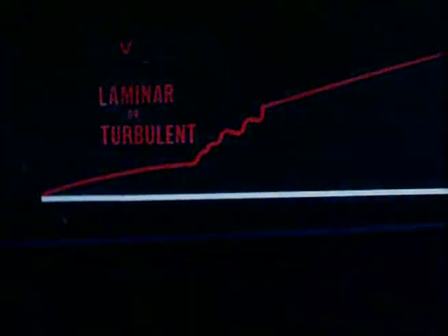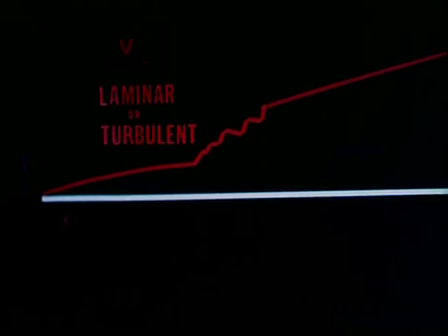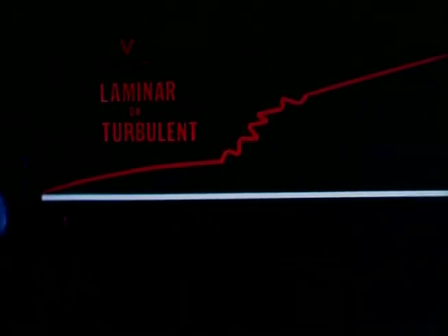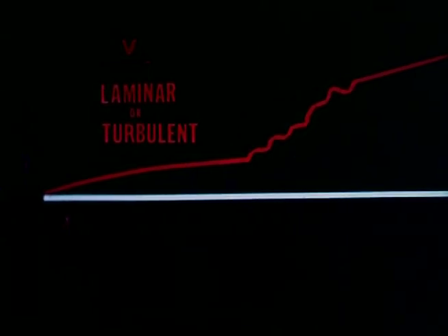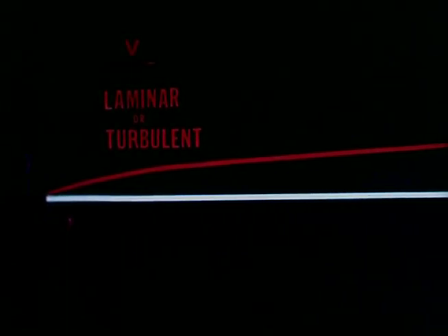Observe that the flow outside the boundary layer is undisturbed and laminar. But even if the outside flow were turbulent, a laminar boundary layer would originate near the leading edge, becoming turbulent later. Outside disturbances influence the location of transition. By carefully avoiding disturbances, transitions can be delayed to Reynolds numbers of several million.